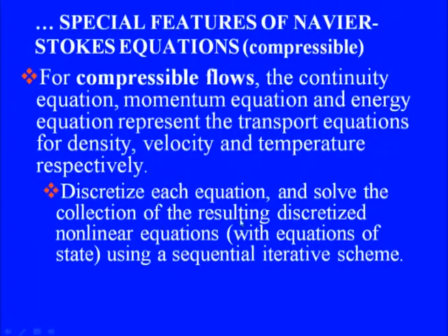So, all that we need to do in this case is discretize each equation, solve the collection of resulting discretized equations which are non-linear, and we have to supplement our equations though by equations of state. For instance, we have pressure coming into the momentum equation, we have got viscosity, we have got thermal conductivity coming in energy equation. So, we need to supply additional equations for the evaluation of these properties.